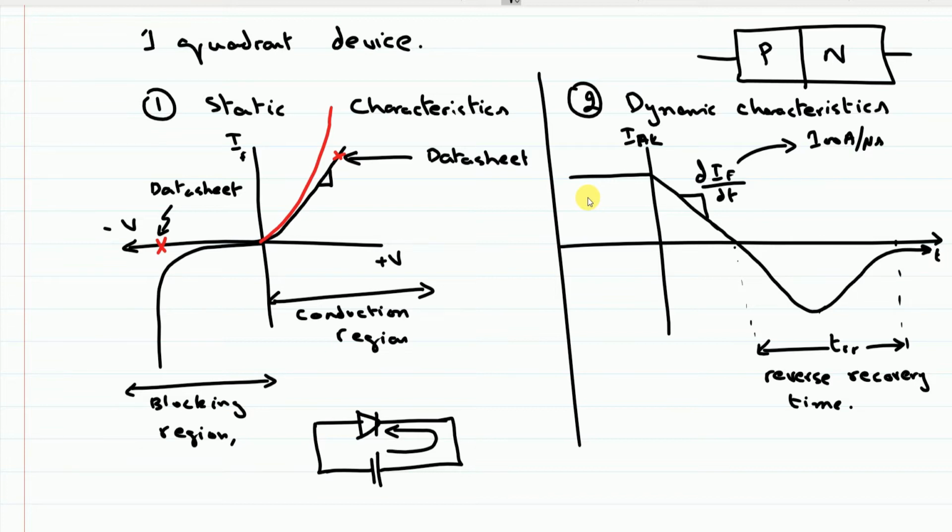This reverse recovery time is an important parameter in defining the maximum switching frequency of a diode. You may see that a line frequency diode fails under switch mode power supply operation, where the switching frequency is as high as maybe 25 kilohertz or 30 kilohertz. It is because that diode does not have enough time to recombine the charges before the new cycle appears. Therefore there are special kinds of diodes designed to operate at high frequencies that are still able to conduct large amounts of current. So this TRR is an important factor in deciding the maximum switching frequency of a given diode.